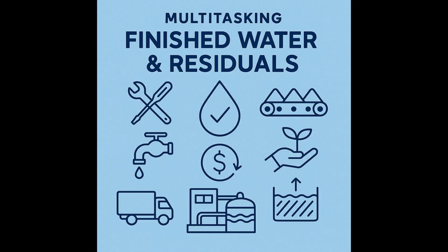Critically important. They're responsible for VPA and NPDES compliance. VPA is Virginia Pollution Abatement. NPDES is the National Pollutant Discharge Elimination System. This means collecting specific samples from the residual streams, getting them analyzed, and reporting the results, things like TSS, total suspended solids, percent solids in the sludge cake, pH, sometimes metals. So lots of sampling and paperwork just for the waste side.